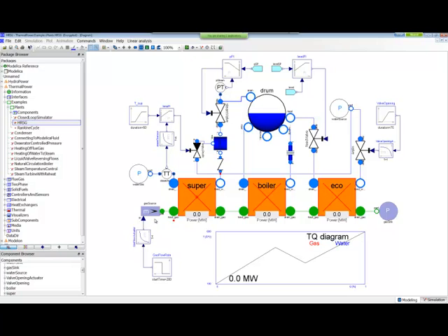Okay, so this is gas coming through the heat exchangers. We have water here that we feed into it. It's heated up here by the gas, goes to drums, and here we take out some water. We boil it actually. We take out some vapor, goes out at the top of the drum, and then it passes the last or the first heat exchanger, so the steam gets superheated, and then it goes to sink, but you can also pass it to for example a steam turbine, and then connect it to a generator.